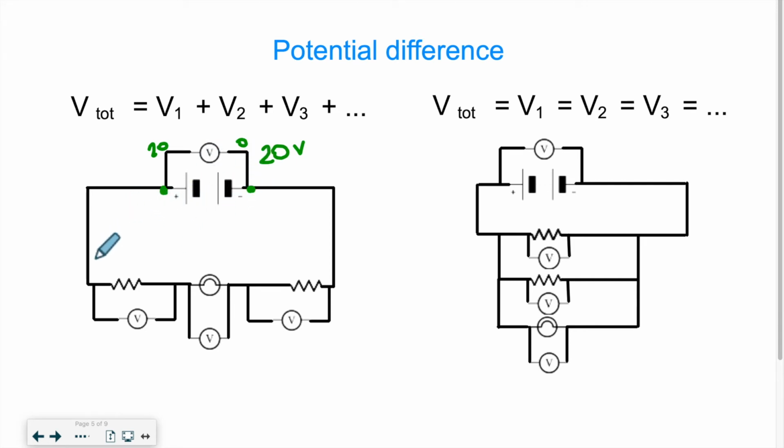Okay, so my electrons leave, and they have 20 volts, and they spend, it just happens that way, 10 volts over here. And then they continue their journey, and let's say they spend 2 volts over here, and here they're going to spend 8, because as I just said, they have to spend everything before they come back. That's the way it works. So if you look carefully, we have 10 and 2 and 8. These numbers add up to the original 20 volts that they left with.